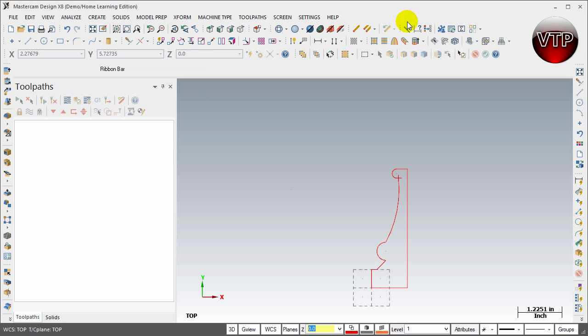It's usually because you've selected something else over here, and the notification does not show as clear as when you're designing a geometry in yellow. So sometimes you just have to press escape and you exit out of whatever you were doing last. So go ahead and left click at the bottom right and drag the box and let go and click on the top left. You're gonna have everything selected, and then come over here.